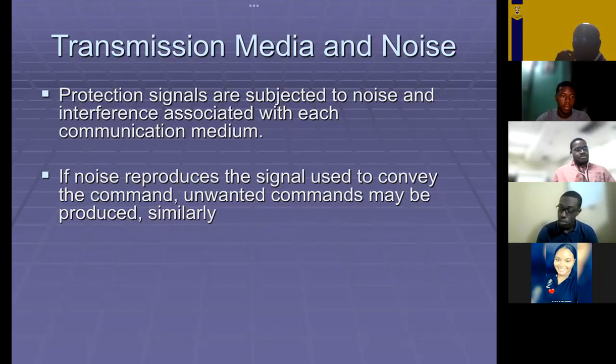Now, the question is, because I have to do that, would I want to put or use microwave in an area that is subject to high winds? No, because that might lead to signal attenuation. It might shift the antenna, and can shift it quite easily, and immediately you lose the line of sight.